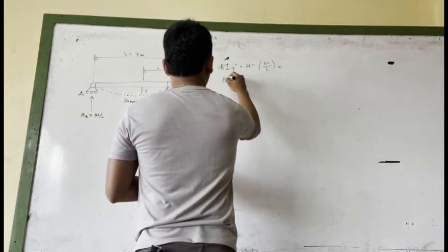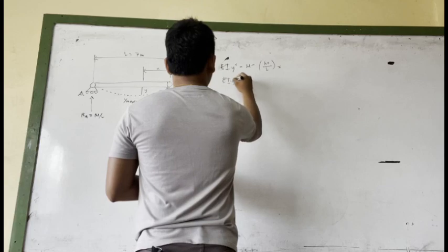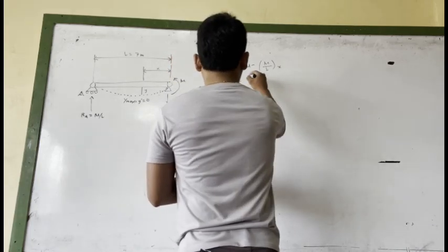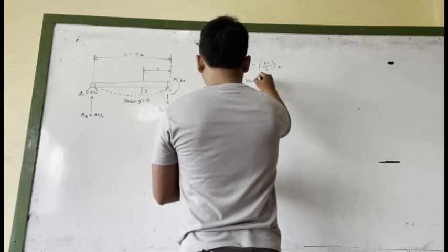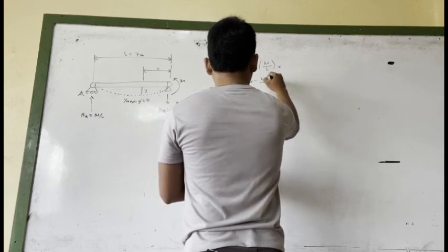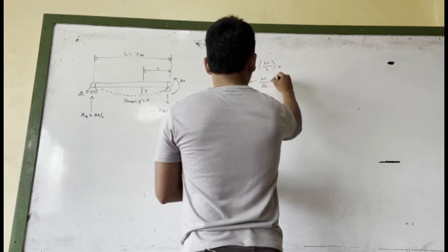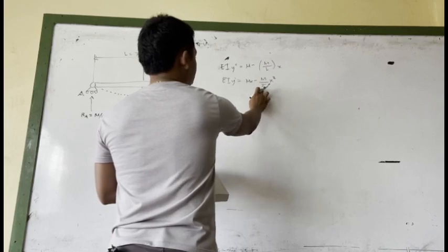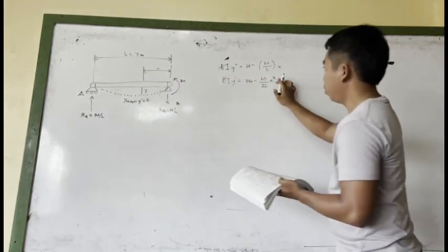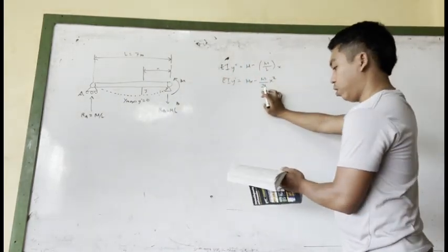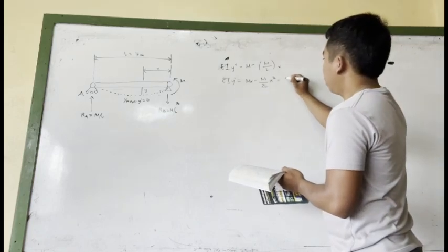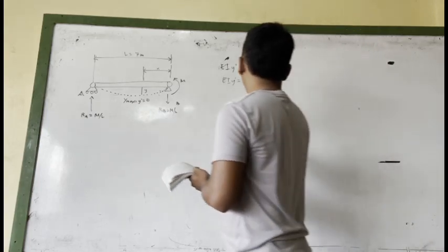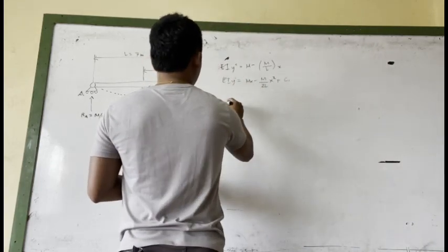So I will directly get the value. This will become Mx minus M over 2L x squared, where the power is brought down to the denominator. So the 2 will be brought down to the denominator, which makes it 2L, plus C1. So C1 for the first integration.